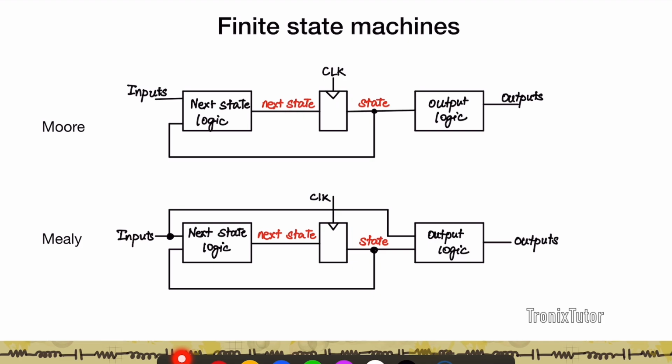So if I'm going to think about coding up a finite state machine, I'm going to have one part of the code which is nothing but a register storing the state variable. I'll have some part of the code implementing the output logic, and another part implementing the next state logic. So that's essentially the way you would implement an FSM based on what you've learned so far: the code has three important parts, the register part, the output logic part, and the next state logic part.